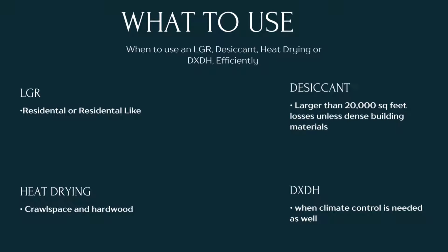You say, well, why would you want to do that? Well, when you're cooling air, an air conditioner is a great dehumidifier. It brings the water out, it causes it to form on the coils, and the water goes running across the parking lot. And it's a good dehumidifier, and it's extra large, so that helps you with that. When you turn heat on it, it heats those coils up and causes you to get extra evaporation out of it, or extra water removal.